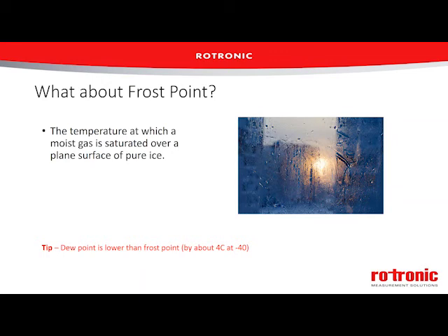One of the interesting characteristics of water is it does not always freeze at 0 or going below 0. We get a phenomenon called supercooled water. And so we can actually have liquid water down to temperatures well below freezing. I've seen it down at -10 or -20 C, and quite often this shows up on chilled mirror hygrometers.